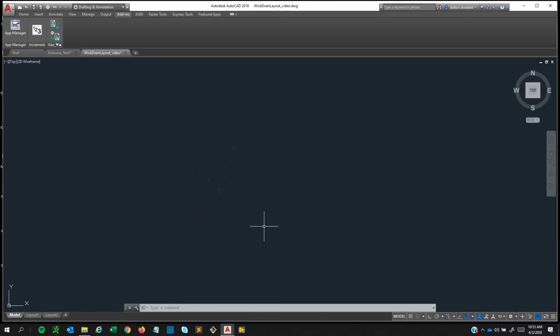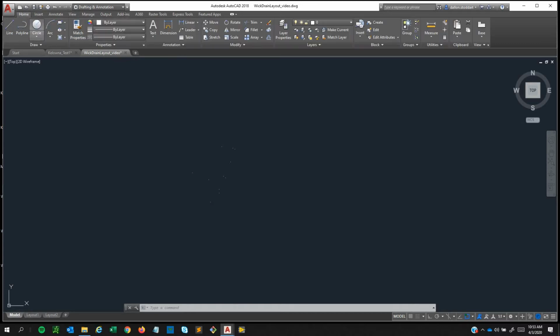I'm going to import a drawing, a PDF drawing overlay in red. So I'm just going to highlight these and just change the by block layer to red, and I'm going to import the PDF in white. I'm not sure if I said that backwards. So now we can save this, and I'm going to go to my file manager and drag and drop my